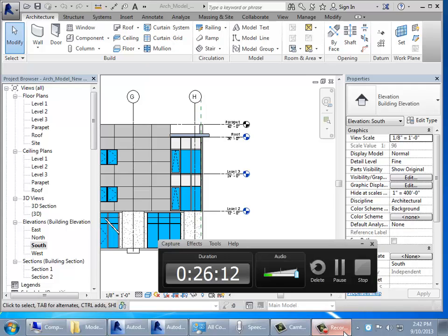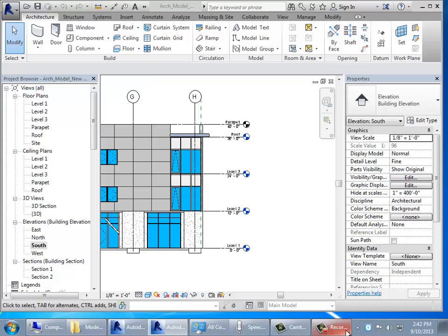They start at level 1 and 50 and then go up. Well, what's going to happen is if you lay the first one out at 100, then you put the next one at 115 or 120 or whatever it is, you can do it that way. Or if you just want to put it at 0, 15, 30, you can move them all up together, and you can move the whole project reference point up too. Either way works, but the more you can lay out properly up front, the better.